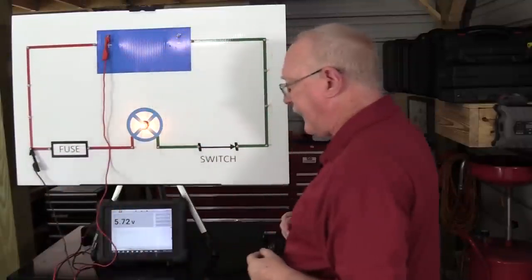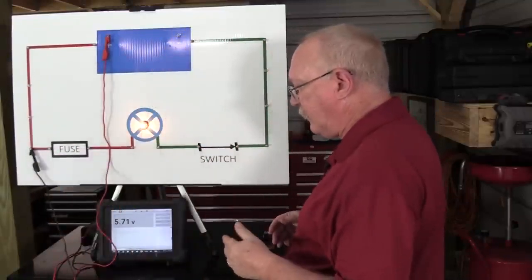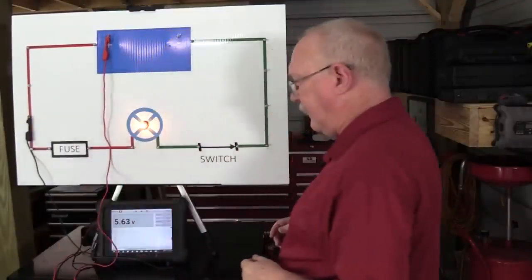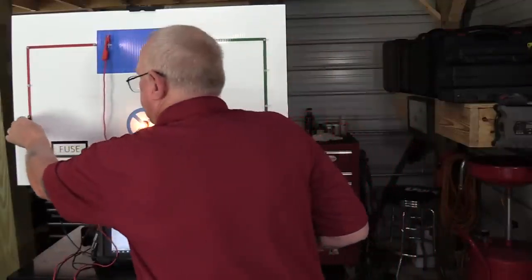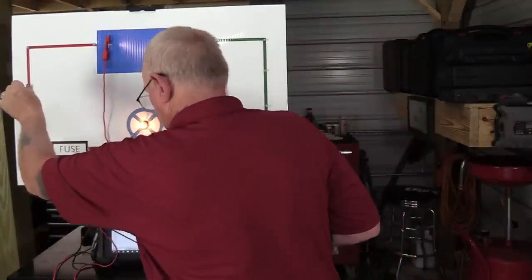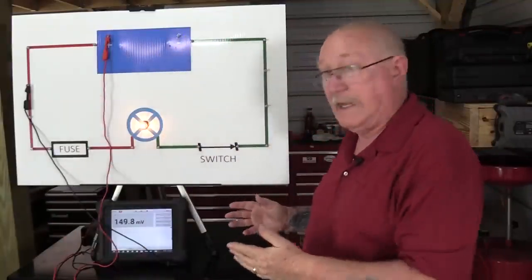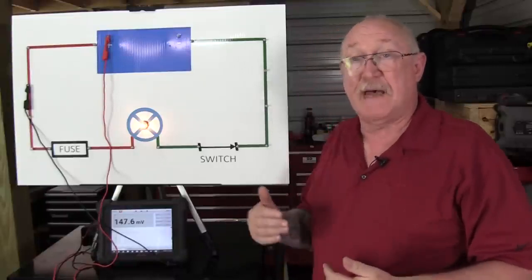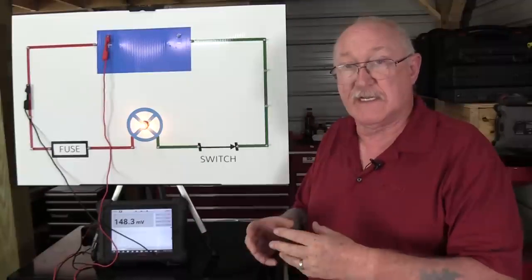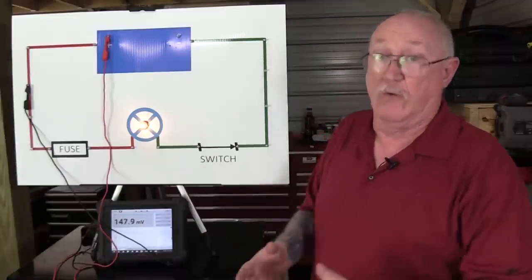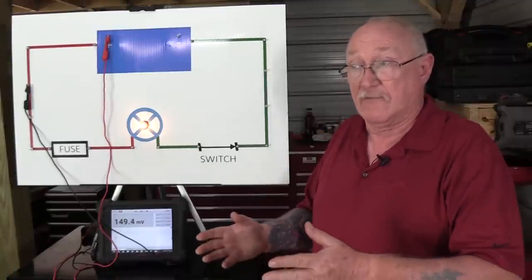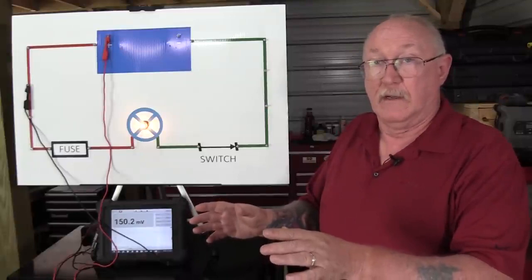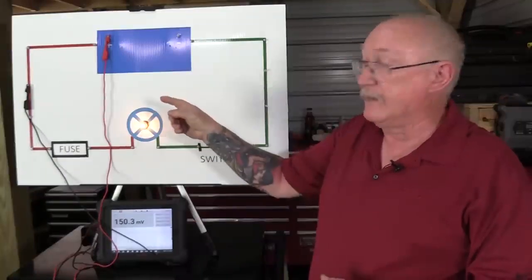And we continue working our way back until we want to see that meter return to maybe a few hundred millivolts. Still not there. All right, next stop. Oh, okay. That's a lot better, isn't it? We got about 150 millivolts. So that's telling me I just passed wherever that source of resistance is that's requiring 5.5 volts or more to work in order to get that current pushed through it. I just passed it.